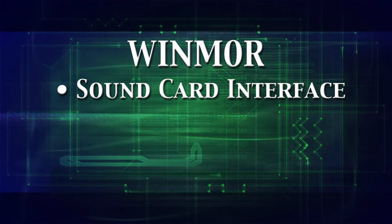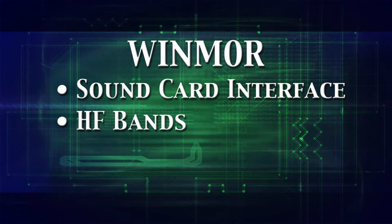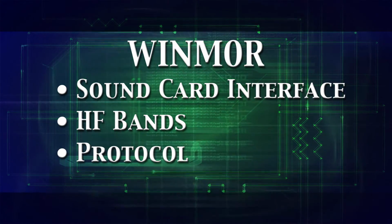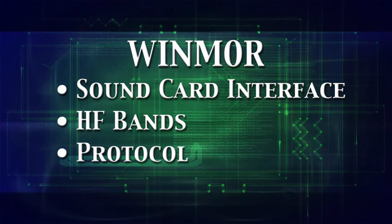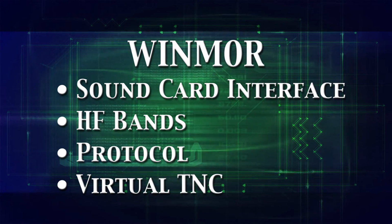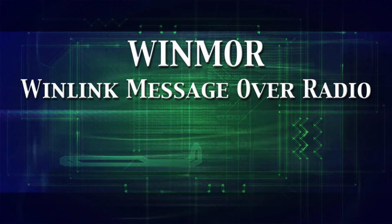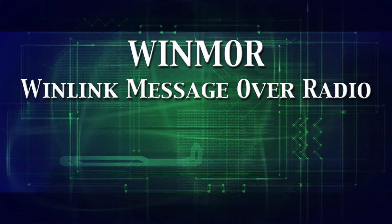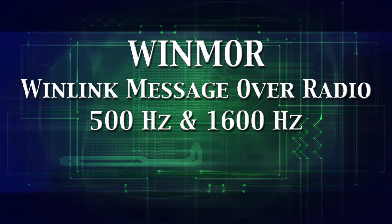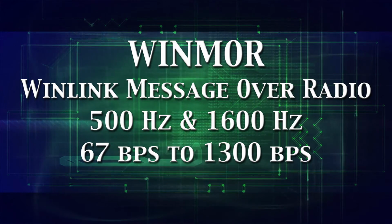Winmor is based on a computer sound card to radio interface and is typically used for connection to the Winlink system on the HF or high-frequency amateur bands. Technically speaking, Winmor is called a protocol, and RMS Express implements this protocol with a Winmor Virtual TNC, or Winmor Virtual Terminal Node Controller, which we'll see in a few minutes. Winmor stands for Winlink Message over Radio and has two modes, either 500 or 1600 Hz in bandwidth, and provides speeds ranging from 67 to 1300 bits per second.